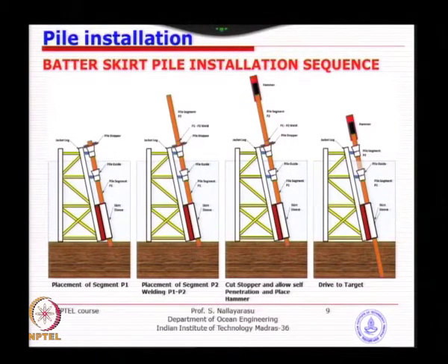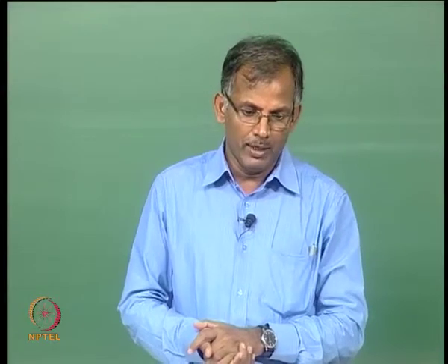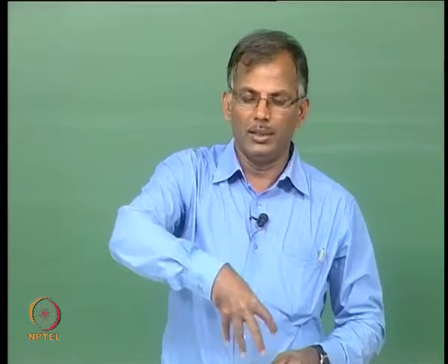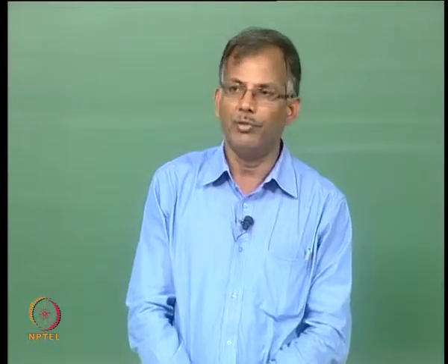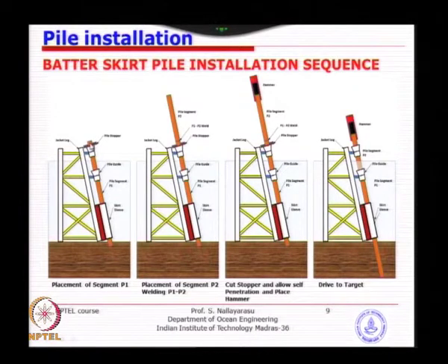Otherwise, what happens if you do not have this? The pile will disappear because of its own weight, and there is very little resistance from the top layer of the soil. The pile will go inside, and that is the end of this project, because you can't retrieve the pile. If it has gone inside, it is very hard for anybody to enter, unless you have hydraulic devices which can be lowered, expanded and lifted up, but many times it is very hard. That is why pile disappearance has happened in the past, because of under prediction or over prediction of the lengths required.